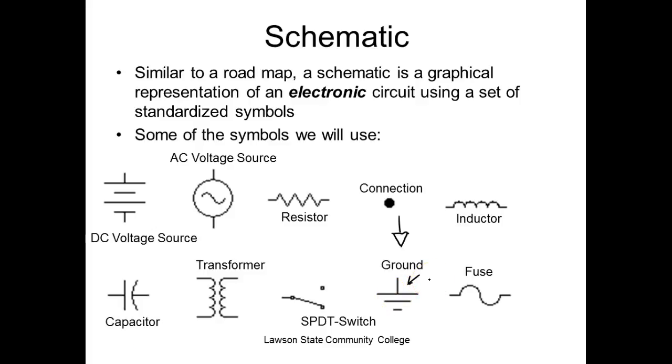Okay. So what's the difference between a ground and a common? Not necessarily. God, I hope not. I mean, I'd be in trouble. My cell phone runs on a common. My car has a common in it. Common is just a common point of a circuit. Right. Ground goes to earth. Goes to earth ground, right. And you need to understand the difference. This is one of the most unusual, and even in technical manuals, this is a misused term. You need to know the difference between a common and a ground, right?